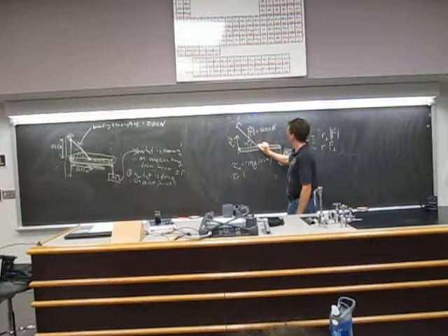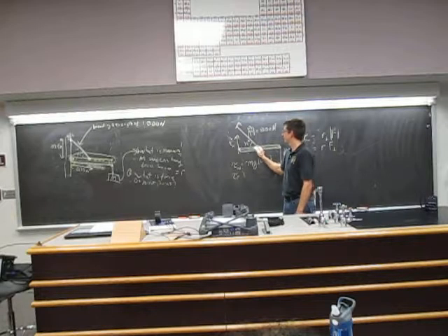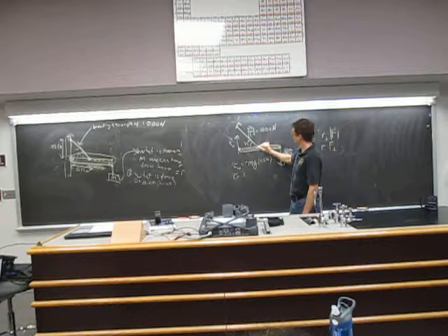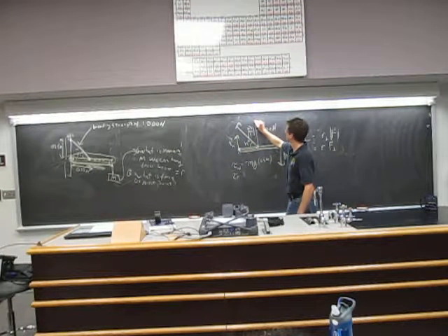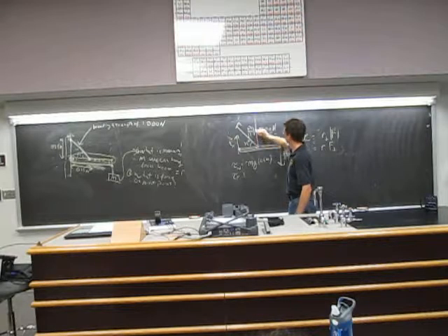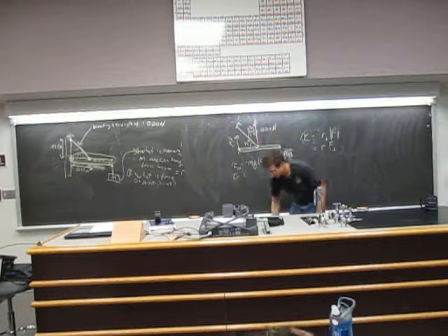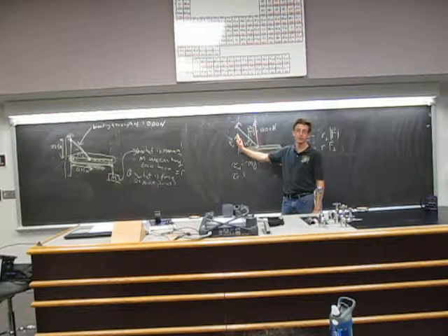The tension force goes off like this, the R goes like this, that's the distance from here to here. The perpendicular component of this force is this component. Why is it not from the pivot drawn that way? You could just draw it that way too. Same component of force.